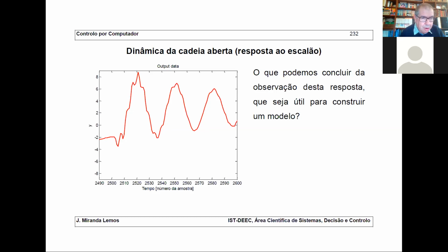Okay, what do you think? Is this noise? These deviations with respect to the... is this noise? I would say so, but it might also be another pair of conjugate poles at higher frequencies, maybe with lower amplitudes. Actually, it is. You can model your bar as a mass that is oscillating.